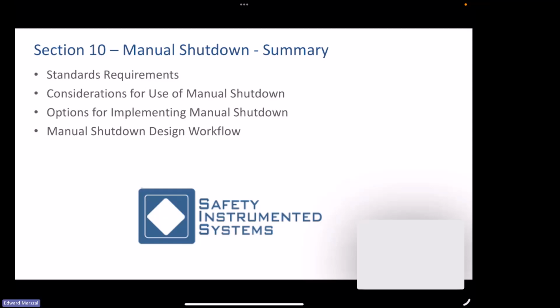So I'll summarize the answer by saying the ability to respond to a pre-alarm and the ability and desire to respond to an alarm that indicates that the SIS didn't activate to take a manual action is very situationally dependent, and you can't always tie them together. Next question, Chris.